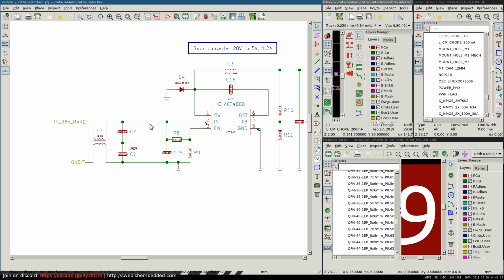I could even place some placeholders for inductors here, and maybe the differential mode filtering here, because once the PCB is completed, it's possible to experiment with different components and take measurements of the noise coming out of this thing, and then do actual calculations for the filter and the values of the components, to make sure that the whole thing remains stable under a wide range of operating conditions.